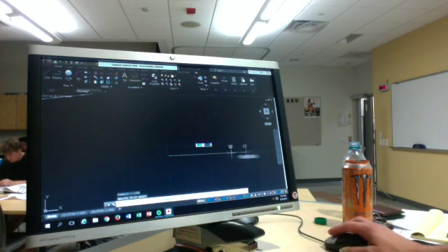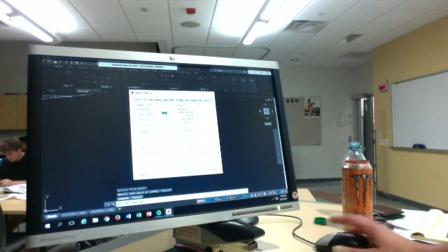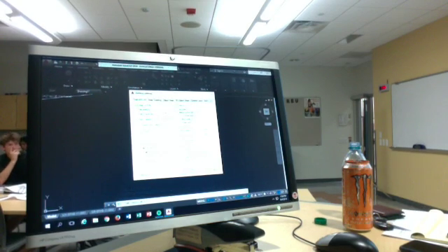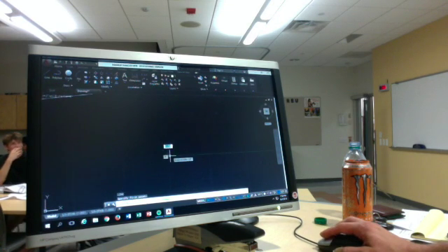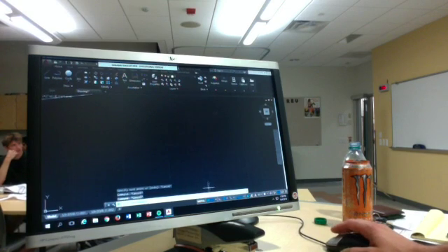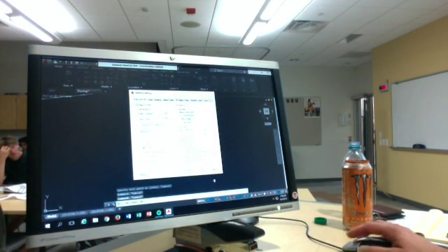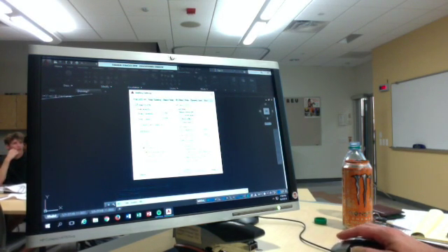It goes by 1 unit. Whereas when we go into our grid settings, let's change this down to, let's say, 1/8 of an inch, 0.125. Now when we change that, and we go to snap, it goes by 1/8 inch intervals. On top of that, if you're zoomed in or super zoomed out, you can change your grid spacing, not just the snap.